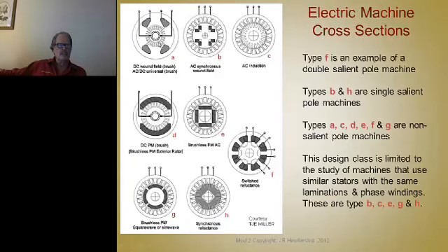So each one of these coils is here's one pole, there's the second pole. So that means that the coils are going to be wound across 180 degrees apart. It'll be a coil there and a coil there, and then pairs of those coils stepped all the way around in a lapped fashion. So as this rotor rotates, when the current is applied into those coils, it causes the polarity of those coils to be such that they move. That will put that torque component on the conductor, which pushes against the steel teeth of the rotor and causes it to rotate. So it commutates itself, it rotates, but then as soon as it rotates, it shorts out the next bar and energizes the next coil and shorts out the one before it.